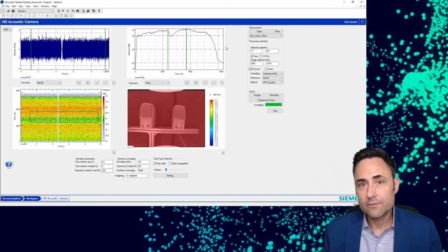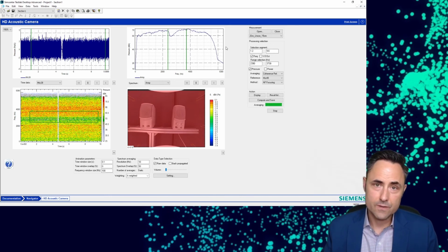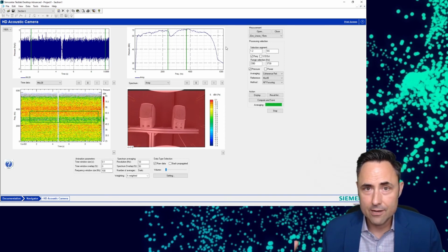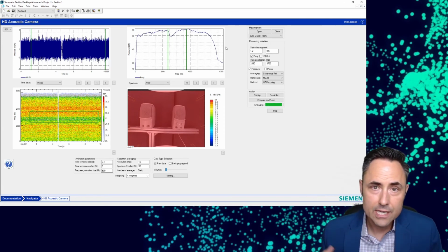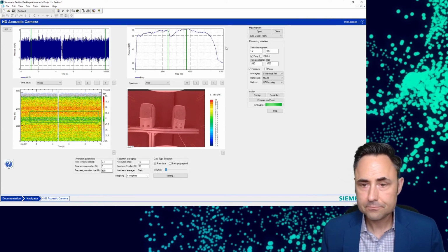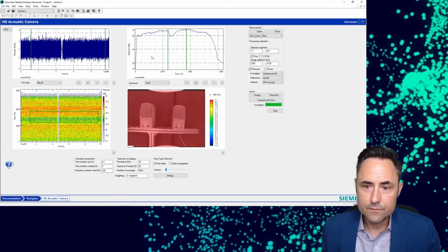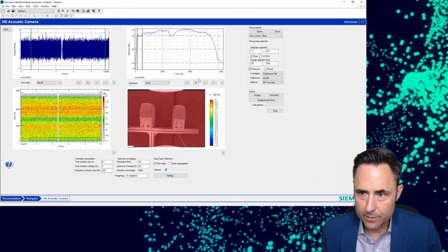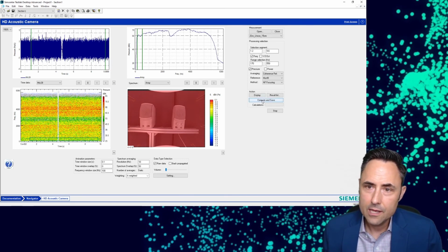Because we have so many microphones in that near field, we can compensate for the fact that the environment is a little bit chaotic. We're capturing enough of the sound energy over all of our microphones to be able to make some sense of it. One of the benefits of this technique is, if I show you what the localization in beamforming looks like for some low frequency, I've selected 170 hertz to 550 hertz, and I'll just grab some time here. I'm just saying, show me where this low frequency energy comes from.